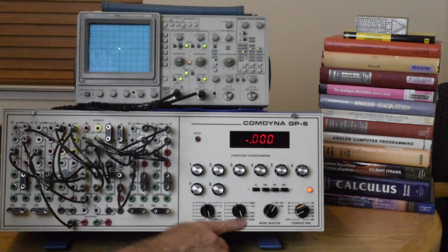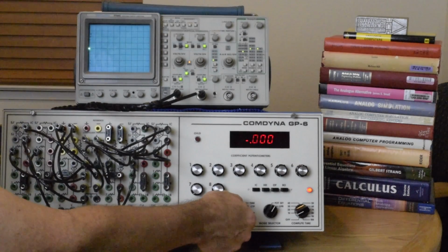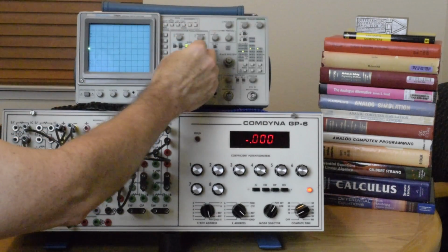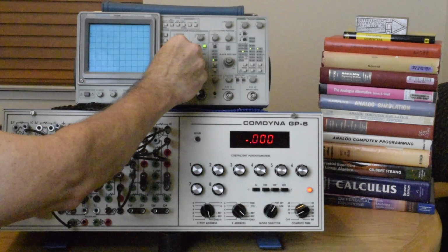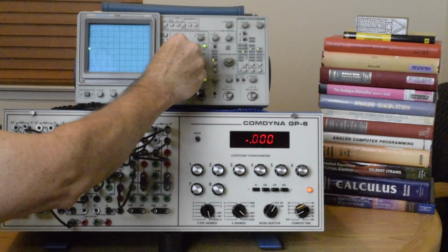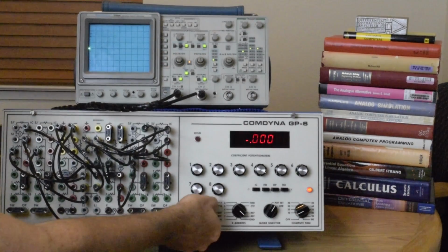And the same thing for the x-axis or time axis. We can see that's pretty well at 0, and there, or sorry, at -10. There, if it was off, I would adjust the channel 1 calibration because that drives the x-axis.